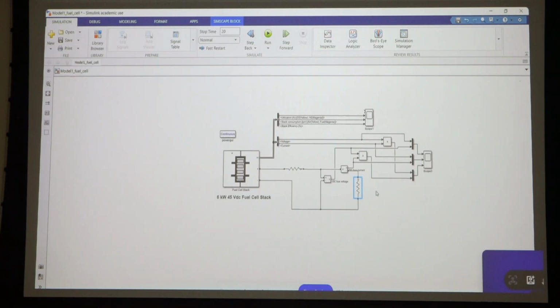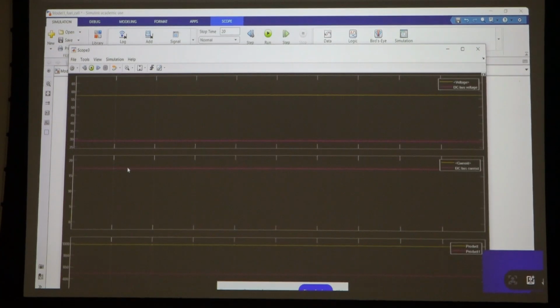Similarly, here we are inserting this component, this is an ammeter for current measurement. So we place it in series. This one actually goes here. So this is the current supplied by this electrolyzer fuel cell, and this one the current we are measuring from here. That means the second channel of this scope measured current. Here we can see this is the second. Both currents, this is a series circuit, so that is why both parameters are the same. You see, same.